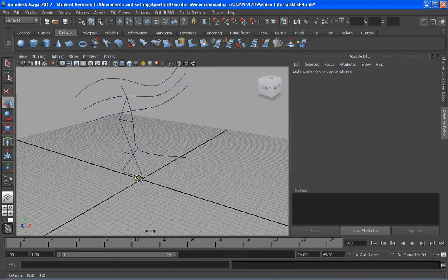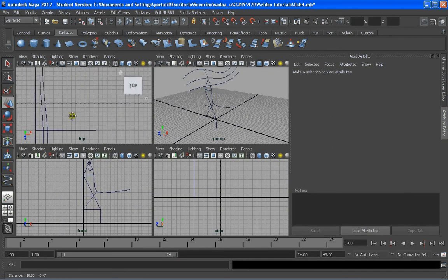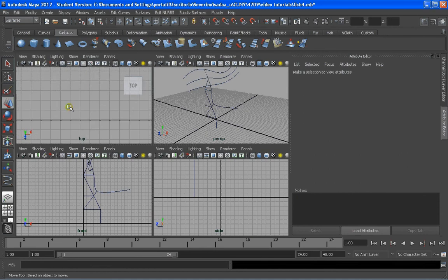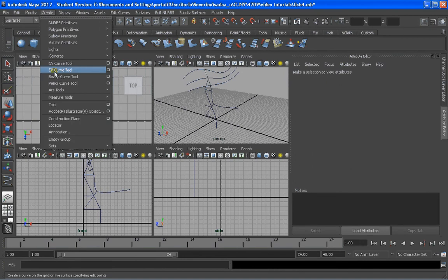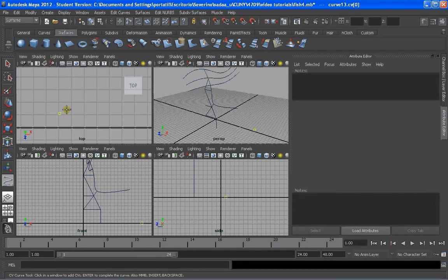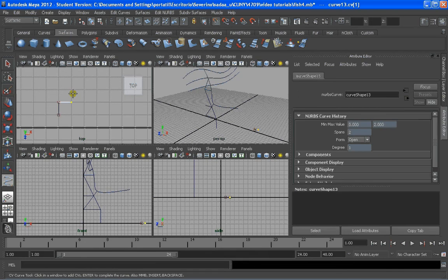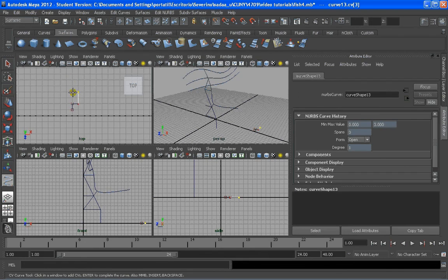So what we need to do now is just draw a couple of profiles, which are the sections of this. I'm going to draw 2 examples. I'm going to go to the front, to the top view, and just draw very quickly a couple of samples by creating CB curves. I'm going to do this. Sorry, snap to the grid by X. Don't worry that they look quite ridiculous in the beginning, because then we can deform them very easily.